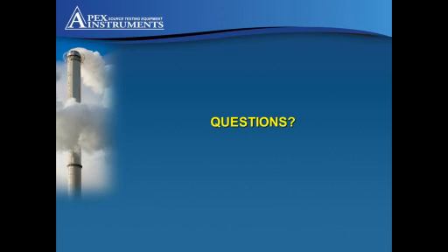We'll look at a couple more questions here that we may have got via email. Normally we can take a direct moisture signal into the sampling console itself. So if there is a real-time moisture instrument giving us a 4 to 20 milliamp output, we can utilize that all the time. And quite often we do see that.